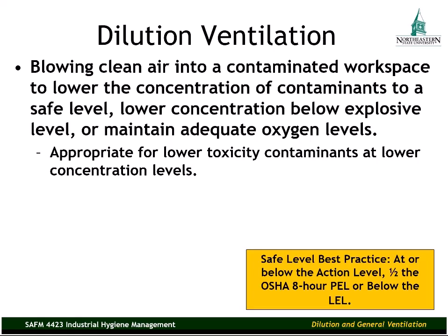And local exhaust ventilation sucks the contaminant out at the source where the contaminant is generated. Again, if high toxicity or high concentrations, LEV would be the better option. Dilution ventilation is where it's not quite as hazardous of a situation.